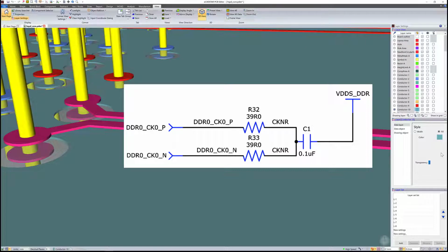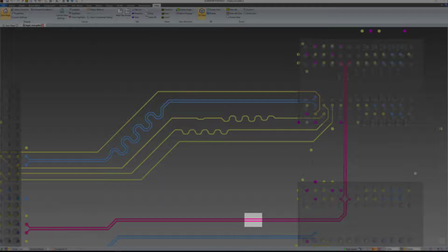Even a well-routed differential pair can pick up noise that propagates in a mode you don't want. There's a DC termination path between the two sides of the differential pair, and an AC termination path from each side through the capacitor to a fixed voltage, so that a sensitive differential signal like this can get from driver to receiver with as little unexpected distortion as possible.